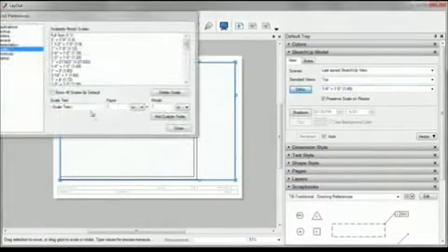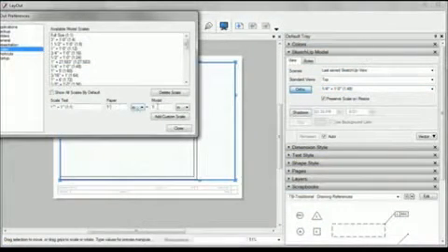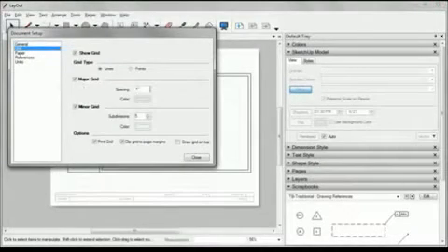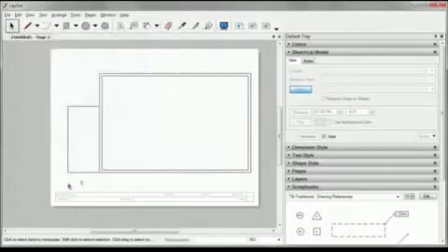Set the building outline to a custom scale in Layout to maximize the use of your paper size. Create a custom grid in Layout to match the irregular scale to make field sketching a breeze.